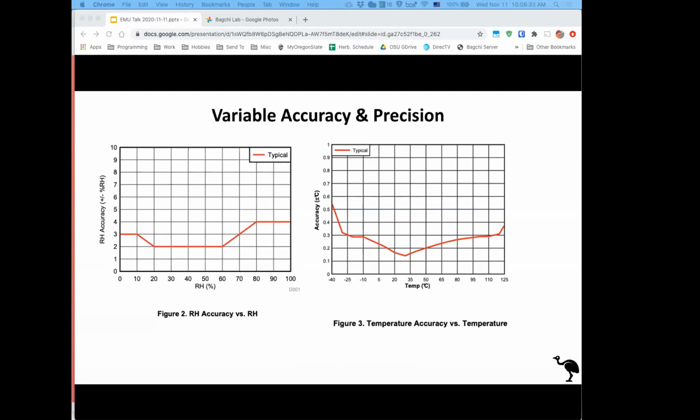We could potentially get that data, but especially for something like temperature, it's actually quite hard because we don't have this gold standard. We don't have something that we can reference to see what our accuracy or precision is. One thing that we could do to try and capture some of that error would be to have multiple sensors. I think someone mentioned this, like having multiple temperature sensors at a single site. But even there, there is going to be some variation in accuracy and precision between the sensors.